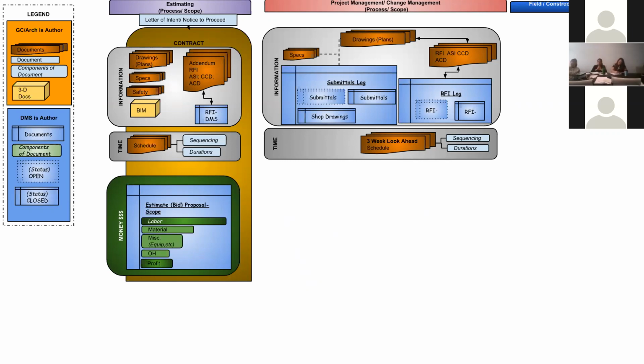So from the framing side, there's three basic phasings for framing. They'll want us to go in, do the fire rated areas and get those approved, which will allow the electricians and mechanical and other plumbing, other critical trades to move forward. And then they'll ask us to come in and do the interior wall building. So we'll actually build the walls, and then there'll be a 3 or 4 week delay, and then they'll ask us to come in and build the ceilings. So for framing, those are the 3 big ways they chunk out framing.